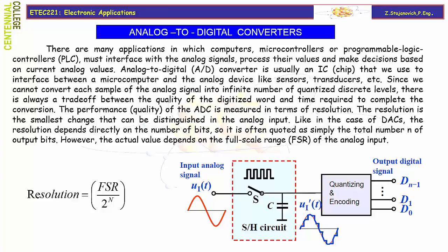converter. Once again, here is a reminder of the process that precedes actually the encoding, analog digital conversion. We're going to sample the input analog signal and we will quantize, and both of those processes will introduce certain degradation of the original analog signal.